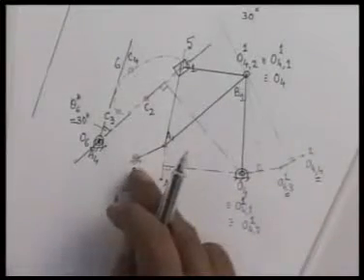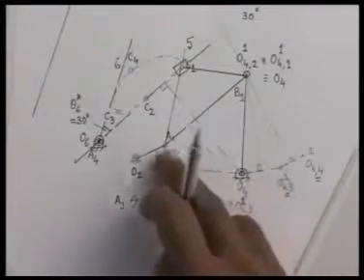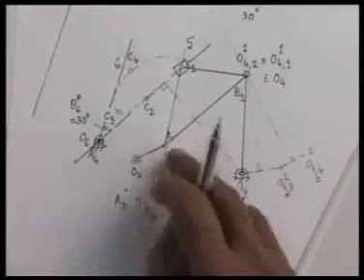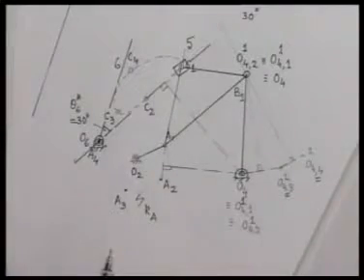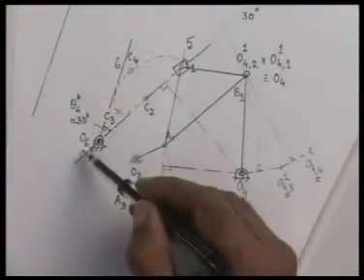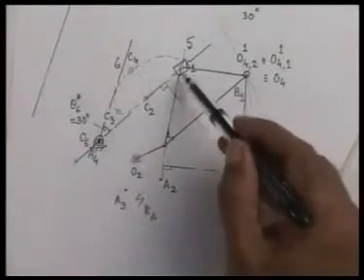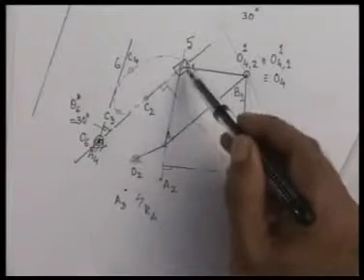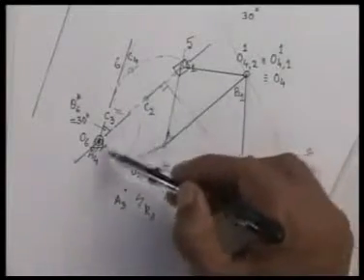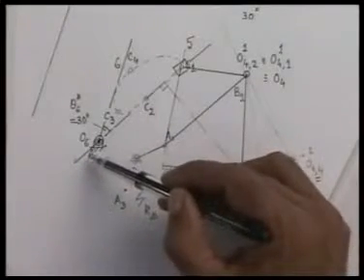We can also verify that this O2, AB, O4 is a crank rocker such that this link A2, A1, the shortest link, can rotate completely. Then we knew that the other fixed hinge O6 connected to the output link 6 must be on this line, which represents approximately the straight line portion of this coupler curve. I have joined C1 and C2 and extended that line.